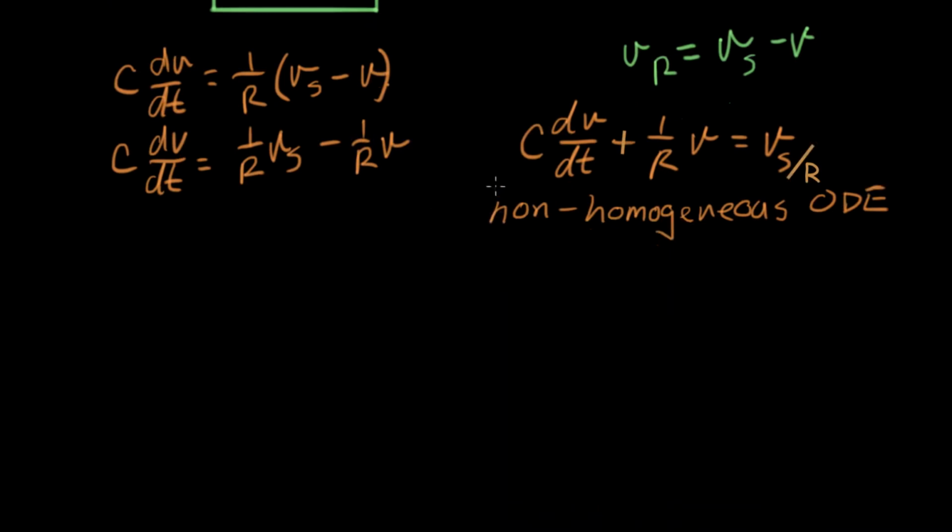This equation is a little tricky to solve because this is not 0 over here. We have a mixture of things going on here. This side of the equation represents the forcing function. This is what the circuit is being driven to by that step response input voltage source. And this side here, we're going to get tied up with the initial conditions that the capacitor has. So there's sort of two things going on here that make this a little more complicated than usual to solve.